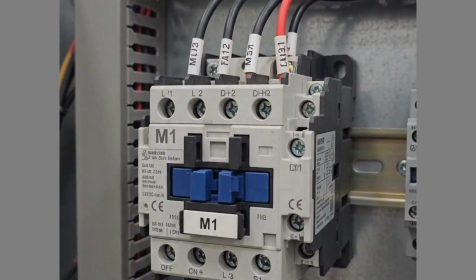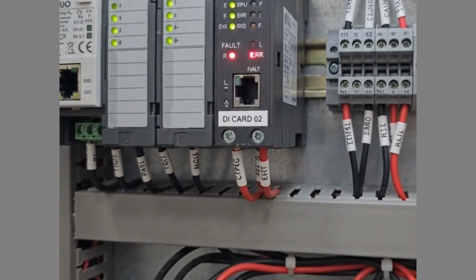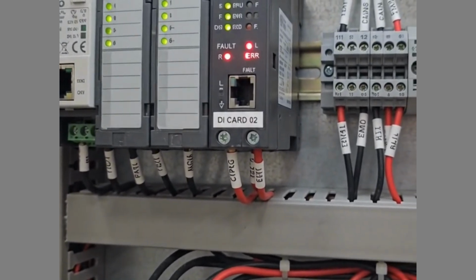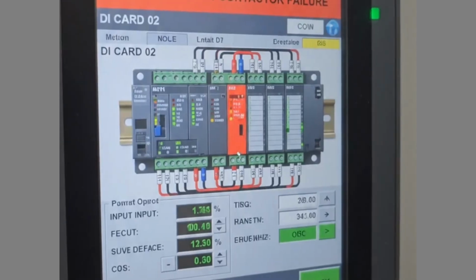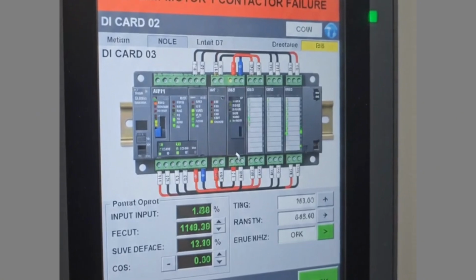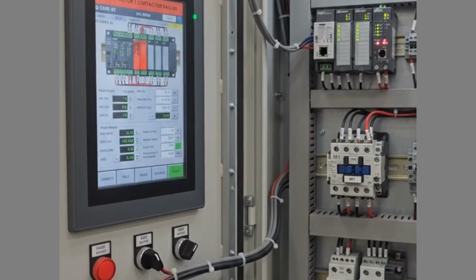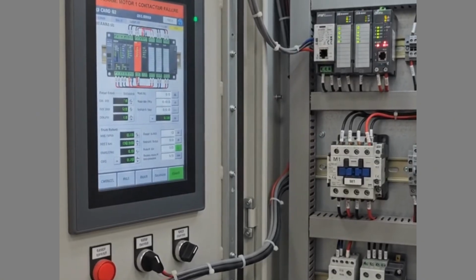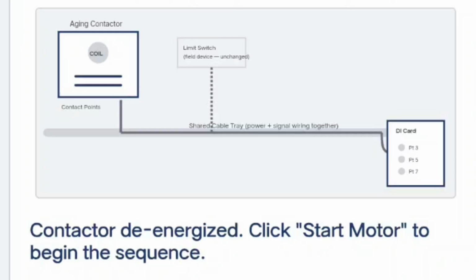And there it was, nearly every fault lined up, within a second or two, with a motor start event on a contactor sharing the same panel. Not every motor start caused a fault, but every fault had a motor start near it. That's the pattern that pointed toward electrical noise, specifically, the transient generated by a contactor closing under load, on aging contacts, without any suppression across them.